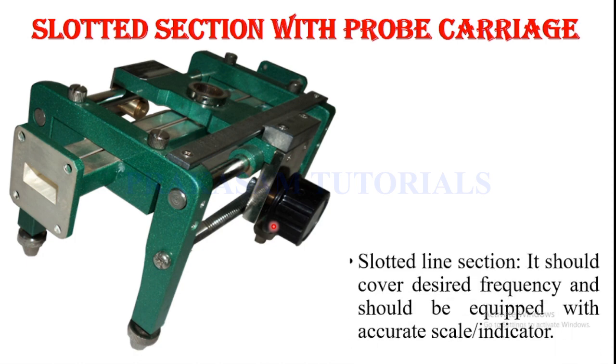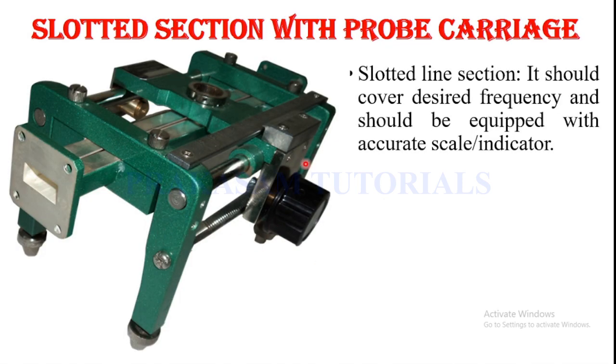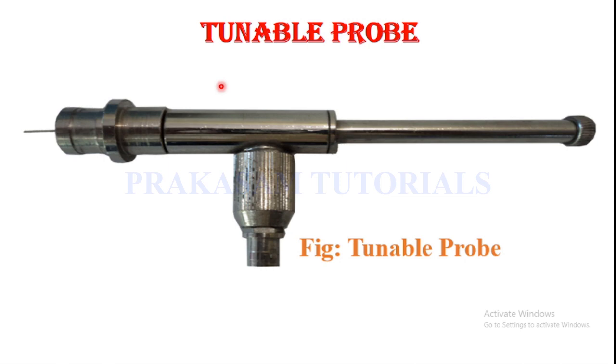And the next waveguide component is the tunable probe. The tunable probe is designed to be used with the slotted line section, and this is the slotted line section. In this center portion, we can use the tunable probe. These are meant for exploring the energy of the electric field in a suitably fabricated section of waveguide. The depth of penetration into a waveguide section is adjustable by the knob of the probe.